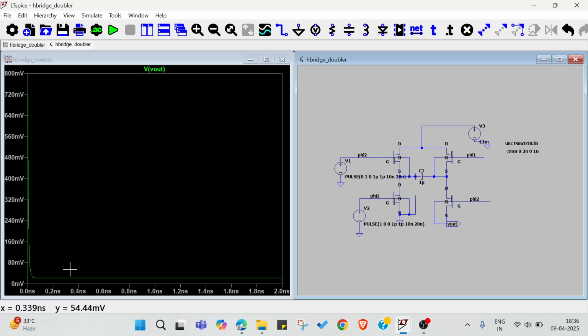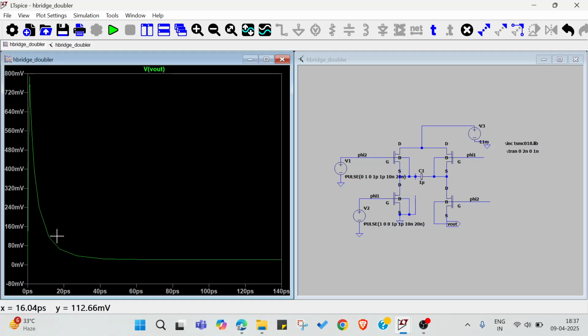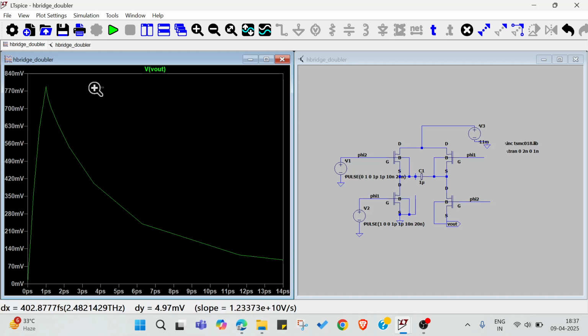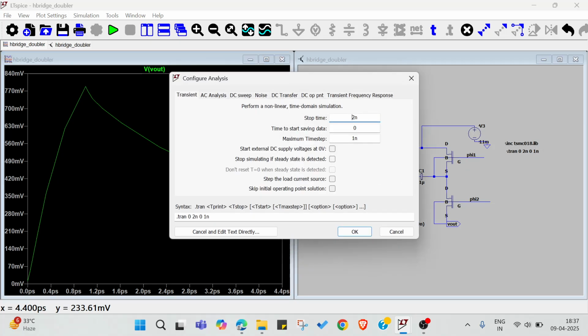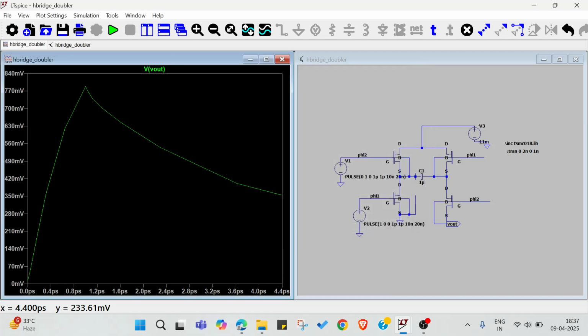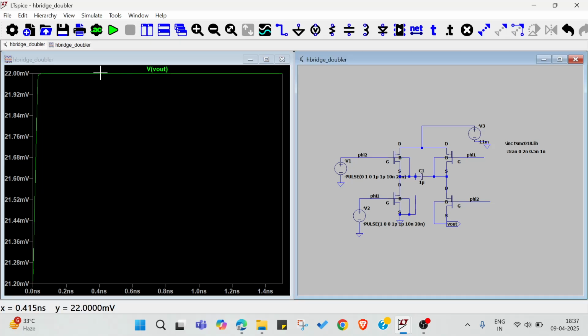So then you can see, it would have been difficult for us to observe the actual voltage because initially we have a sharp peak. So unless this transient settles, we won't be able to see the actual voltage value, right? And for that reason, I gave a skip of 0.4 or 0.5. And then I got it. Now you can see we have a clean signal.